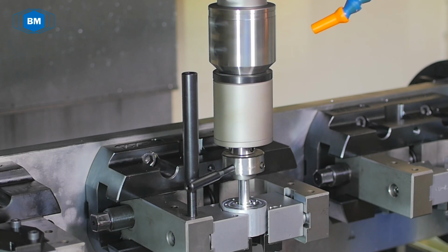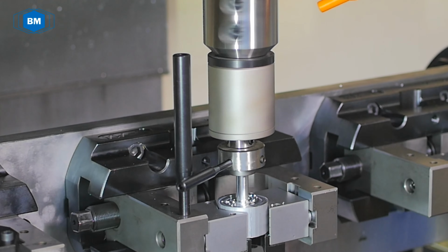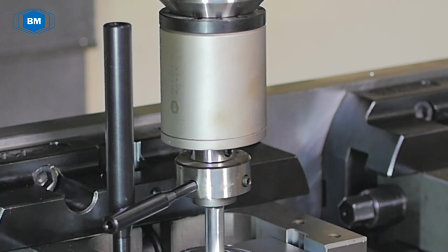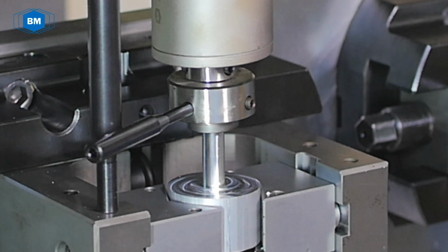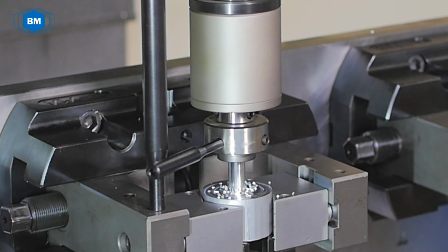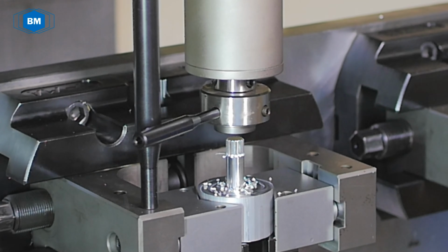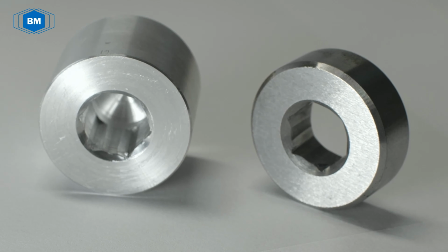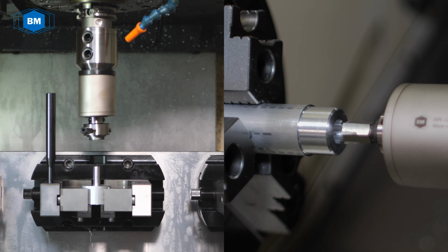The machining center spindle starts, and the Brighetti broaching tool starts spinning. Upon contact, the broach ceases to rotate while the tool body continues to rotate, and thanks to the pendulum oscillatory movement impressed on the broach by the broaching tool, and the vertical feed impressed by the machine tool, you get the desired figure.